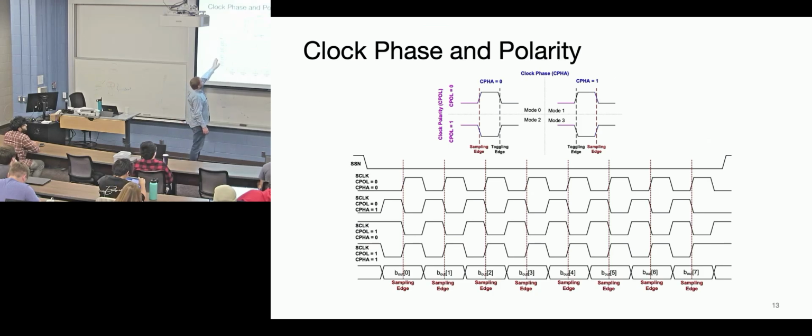And so you have clock polarity 0, so it's normally low, and then you're sampling on the rising edge, so that would be clock phase positive. And so they're just showing you here, I'm going to sample in this. Now, the other one would be clock polarity 0 starting, and then you're clocking a negative edge. So they've just artificially moved this clock back a little bit, just for the purpose of this diagram to show you that this is where you would clock in. That makes sense. Otherwise, you could have 1 clock, but then you'd have to have 4 data versions underneath to make the diagram work. So this is just one way of representing that.